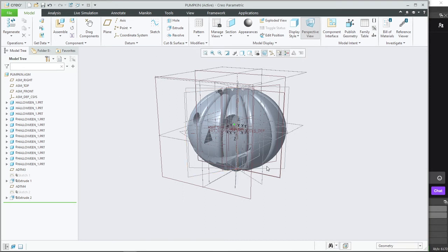Here I'm using millimeters, so I roughly know what I'm doing. But in Blender, the scale is one point. How big is that point? You define it later on, or at any point of the design process. So you could keep it at just 1 point, or give it 1 millimeter, or 1 inch, or give it whatever scale you want to. Blender doesn't care. For Blender, that's 1 unit.